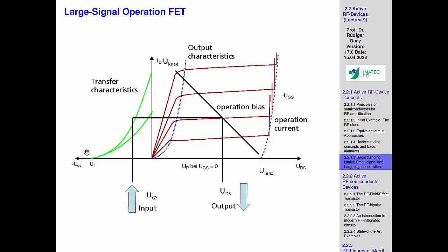It's very clear we also have an upper limit here, and this certainly works against us, because having thin layers means the voltage capability is typically reduced. So the smaller we get, in general, we lose voltage, because some of these things break when you excessively bias them. So that's something which limits us here.